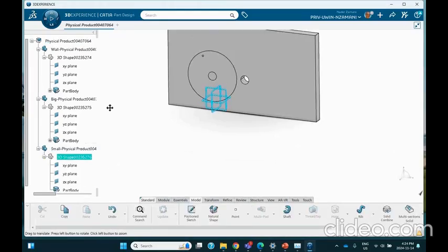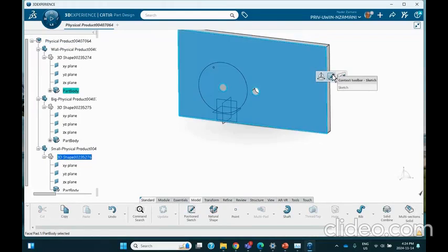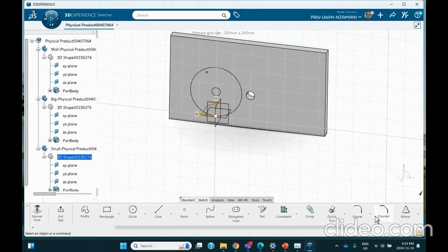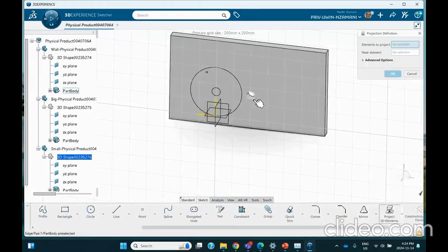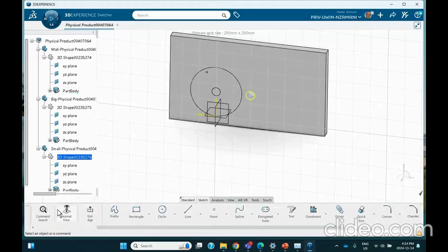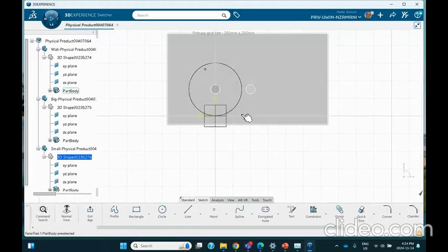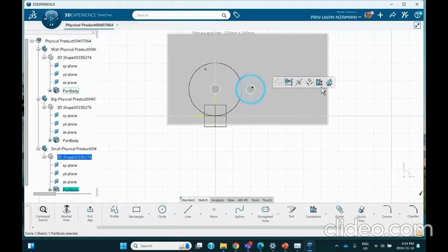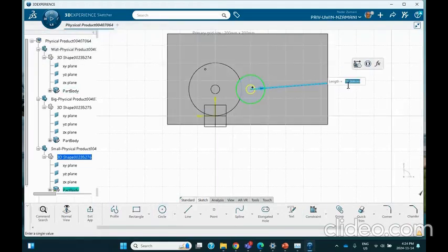Okay. And let's make it, same process. Double click on that plane. I will sketch. Why don't I project that circle? This is just to cut down one operation. So there we are. And then a circle of radius 10. So the view from the front. So circle. I'm going to make this in radius 10. And that makes the two tangent to each other. Good. Exit.